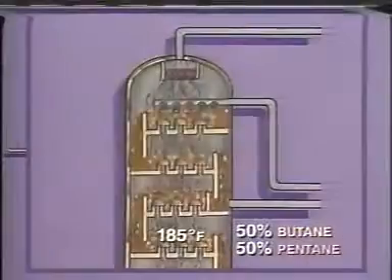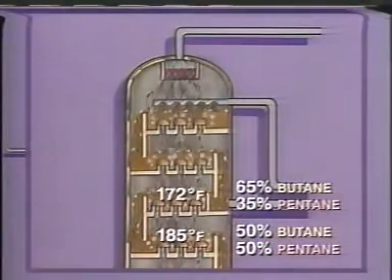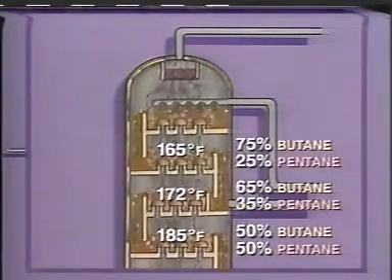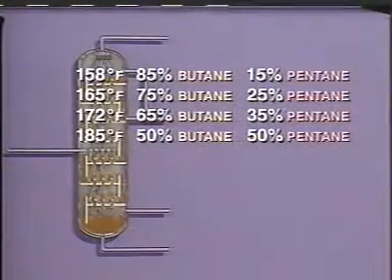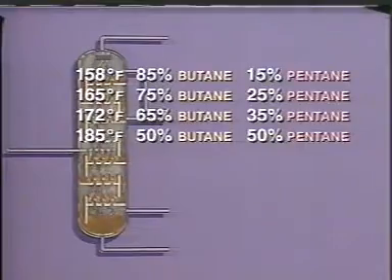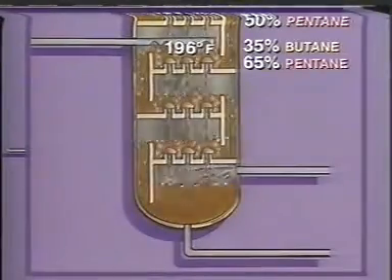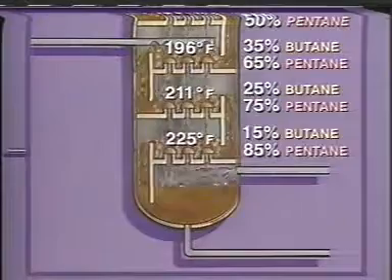In this program, we have reviewed the basic principles that cover how distillation works. In a distillation column, hot rising vapors contact a cooler descending liquid on a series of trays. As a result of this contact, light components in the liquid vaporize and heavy components in the vapor condense. This cycle gradually isolates a different fraction on each tray whose composition is determined by the tray temperature at a given pressure. Since the lowest temperature occurs at the top of the column, a light fraction is formed here. A heavy fraction is isolated at the bottom of the tower where the temperature is highest.